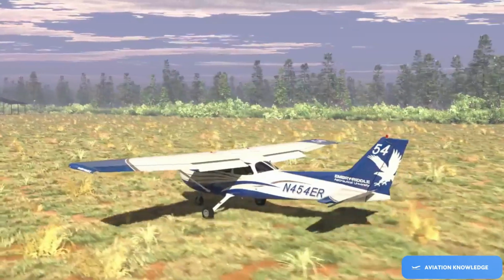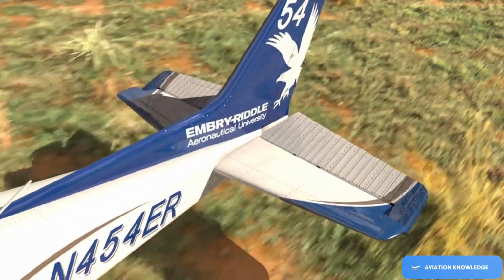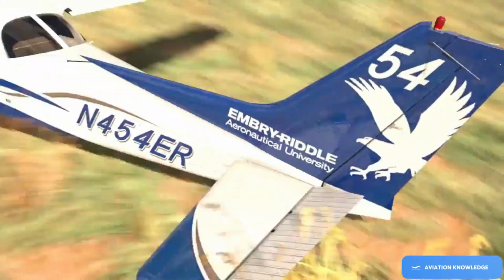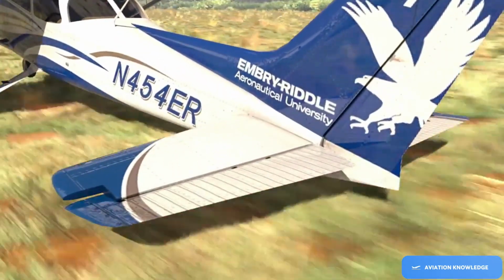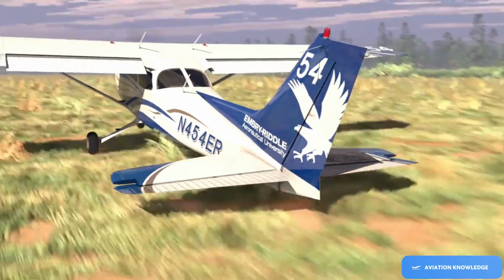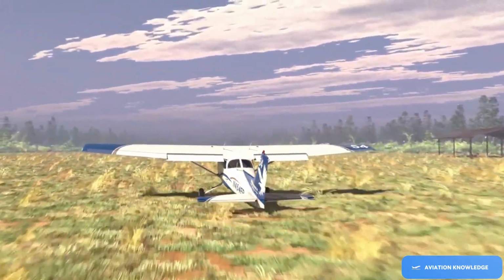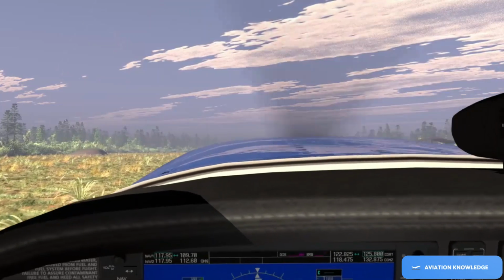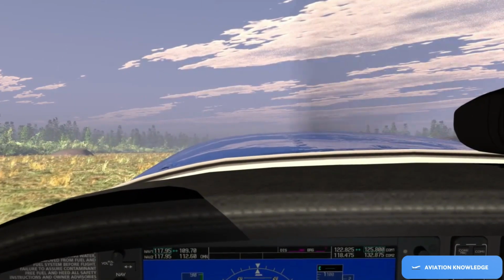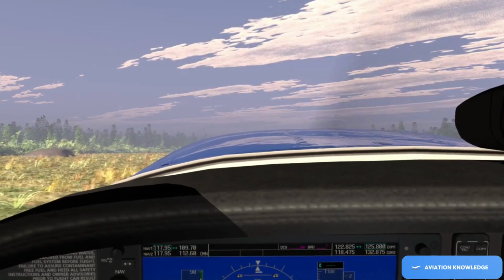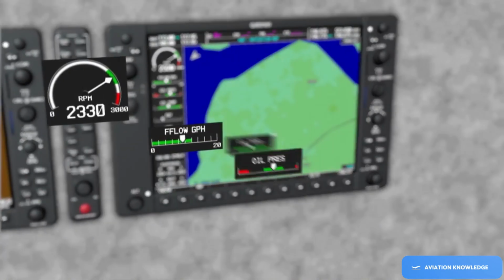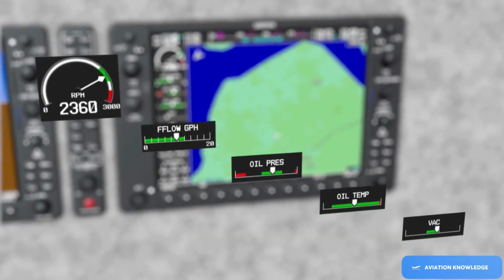As you line up with the runway centerline, smoothly apply full throttle. As you are applying the power, the elevator will become effective almost immediately, so it will be necessary to relax the back pressure on the yoke in order to prevent a tail strike. For a pitch reference, try to keep the nose of the airplane aligned with the treetops at the end of the runway. Check that the engine instruments and tachometer are in the green and make your callouts.